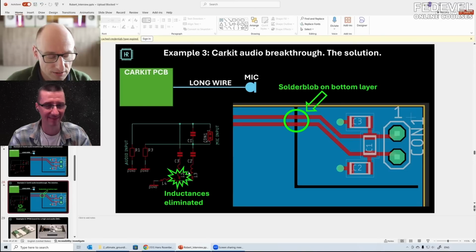The bad thing is, this was an example in one of my YouTube movies, and someone mentioned, hey, I got an EMC guide from a supplier and they're actually showing this as a solution. I didn't ask the guy which supplier that was, because it would be nice to actually download that document and show it. But this is really wrong. And you're violating the rule here that you always should have a single ground plane, which is unobstructed. And we basically have an obstruction here.